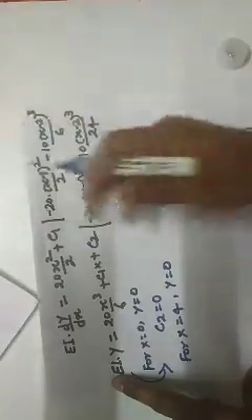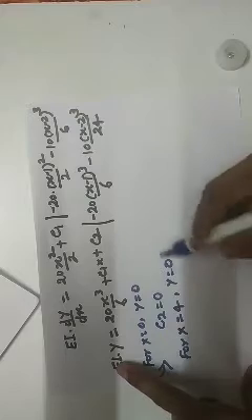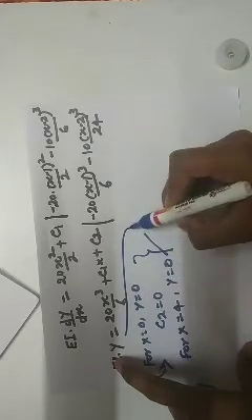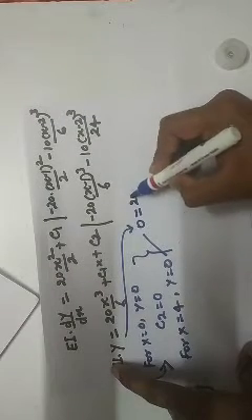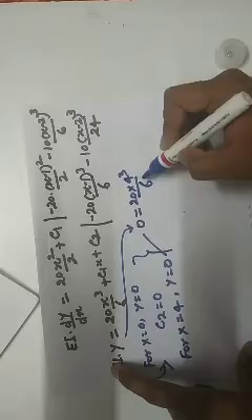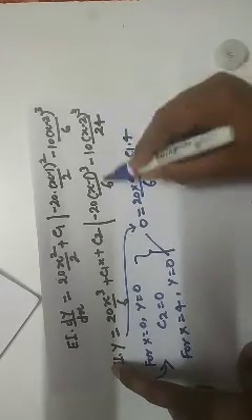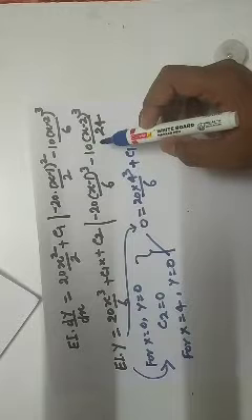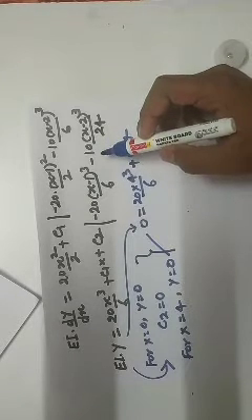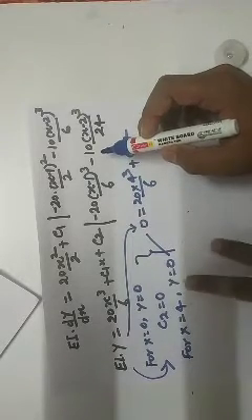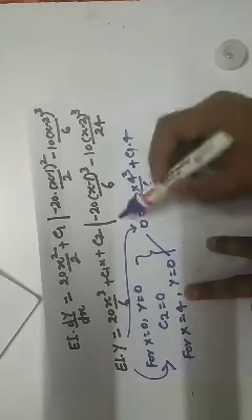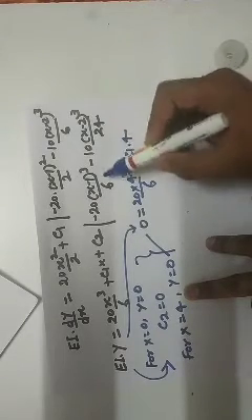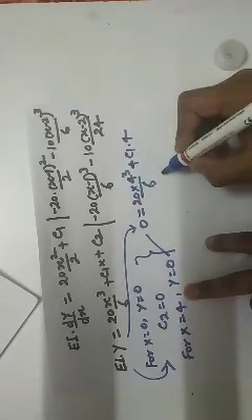Now put this value, then what will be the answer? We will calculate it. y is 0, so put this here, then it will be 0 equal to 20 into 4 cube upon 6, plus C1 into 4, and all these terms will be 0. Why? Because it is a singular function, there is no need to put the value, this is x equal to 4. We are taking the value of x as 4, then we have to put all values in this equation, because we are considering the whole length, then each load is participating. C2 is 0, so there is no need to mention it, right?